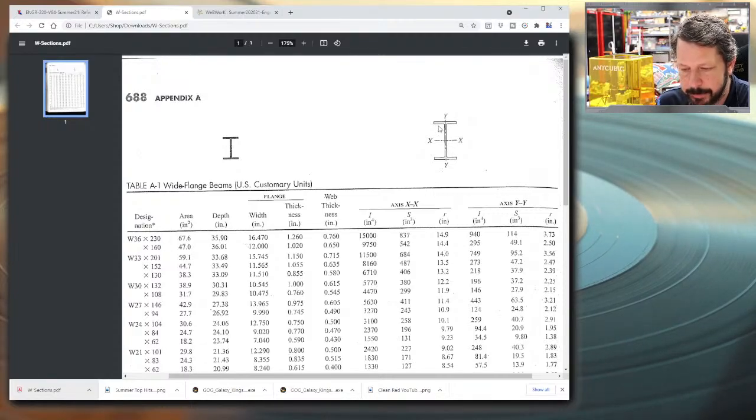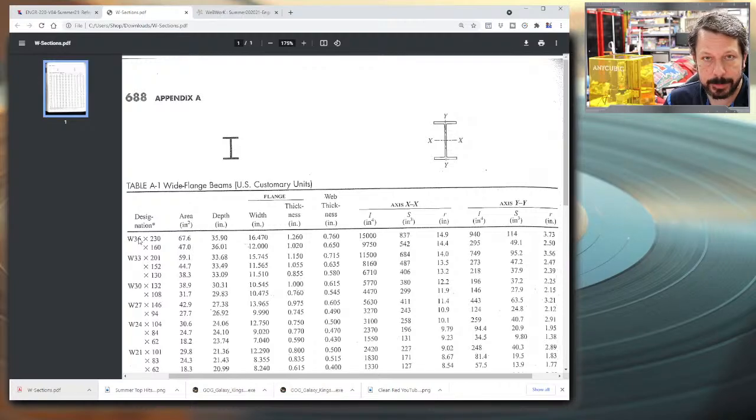these cross-sections are very idealized. A real I-beam is going to have the flanges be tapered towards the end. They're not going to be pure rectangles the whole time. So it's going to be hard to calculate this by measuring the beam. So you go in the charts and find the cross-sectional area. Here's the actual depth of the beam. So it's close to the 36 number, but it's 35.9 inches. So that's how the 36 is nominal. And then you go find the actual depth of it.